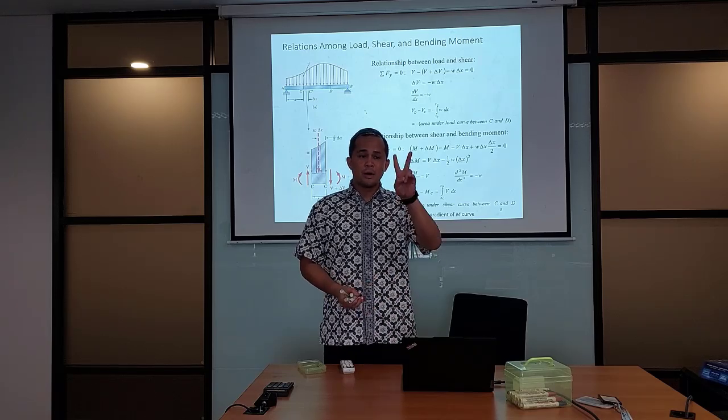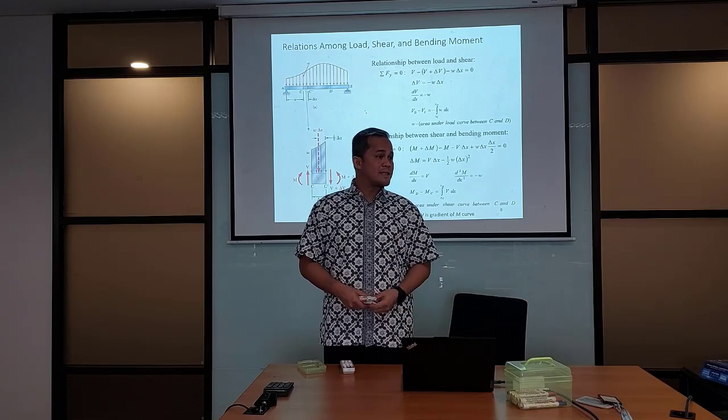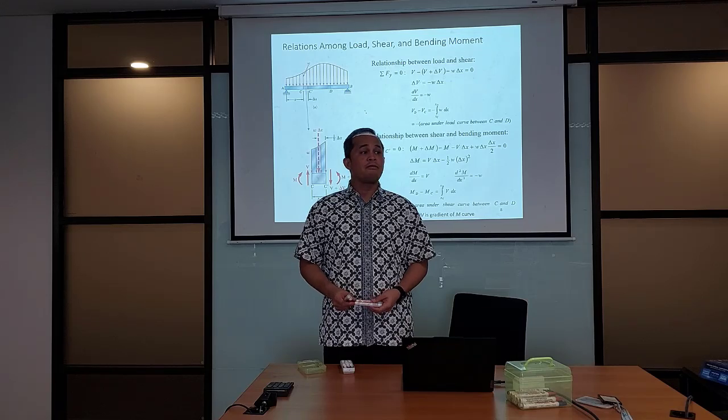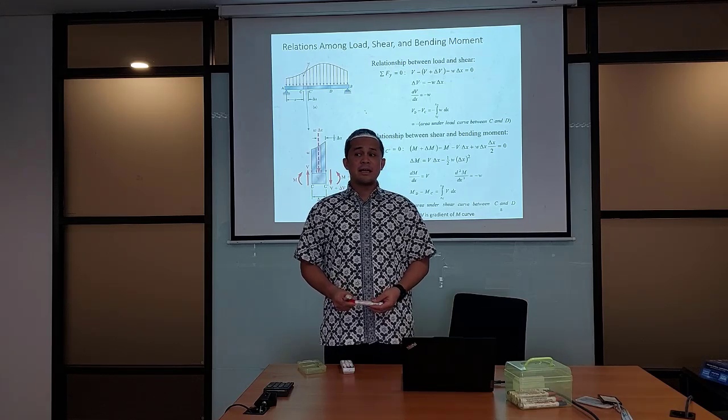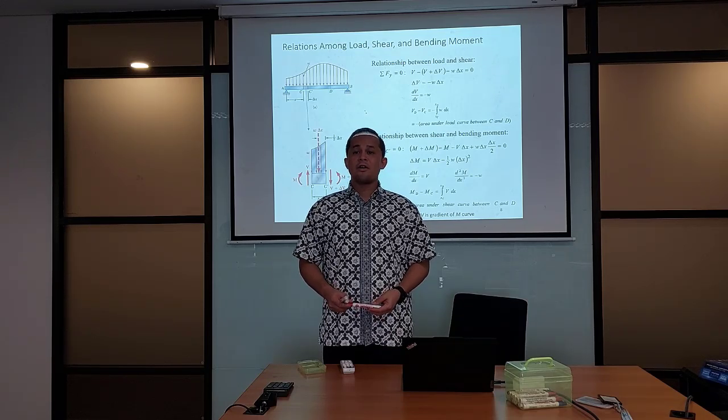The V will give you shear stress. The M will give you normal stress. We haven't yet reached how you determine the shear stress from V. Last meeting, we discussed how you can determine normal stress from bending moment. The equation is sigma equal to MC over I.